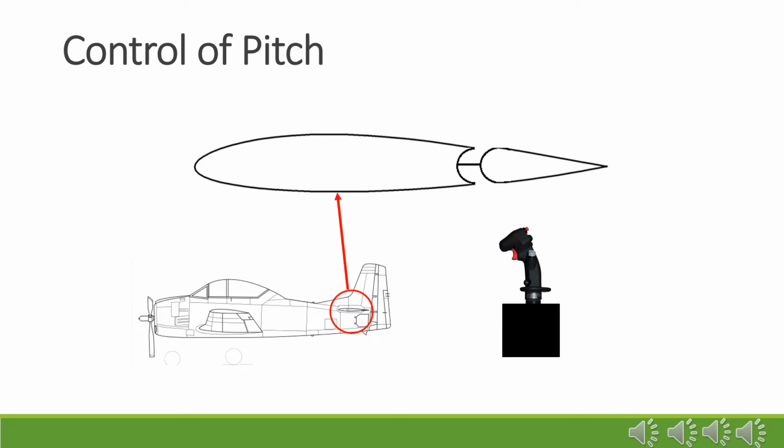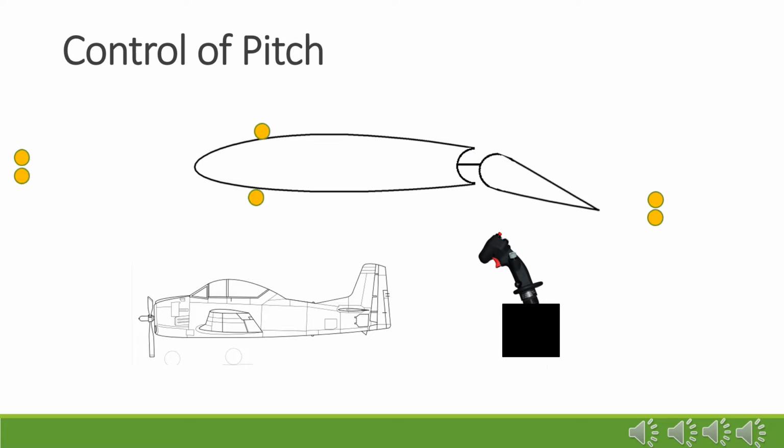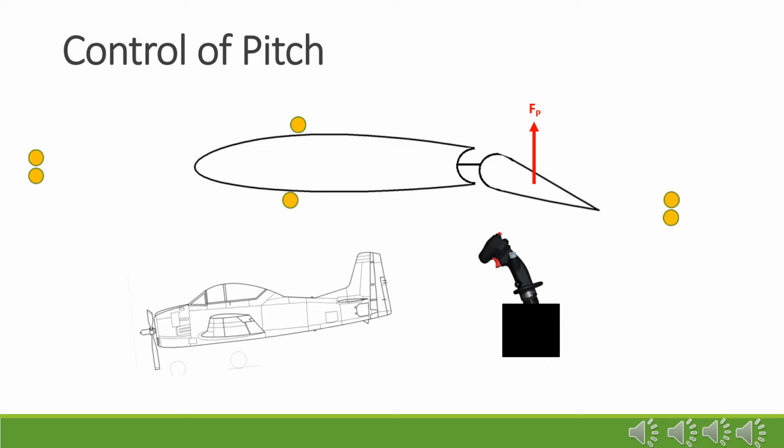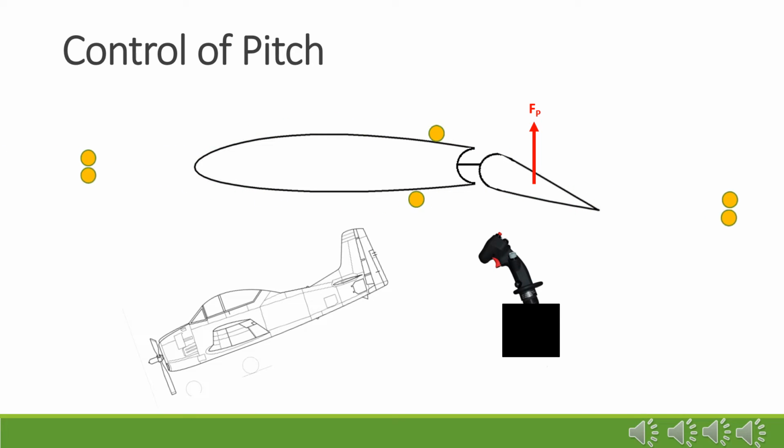With the joystick in the neutral position, the elevators remain in the center position, there are no normal or perpendicular forces, and the drag force is minimized. The aircraft maintains a constant direction. By rotating the control column forward, the elevators are rotated in a downward direction. The normal, drag, and perpendicular forces are applied, with a perpendicular force pushing the tail upward. This upward push on the tail of the aircraft causes the nose of the aircraft to rotate downward, and the aircraft descends.